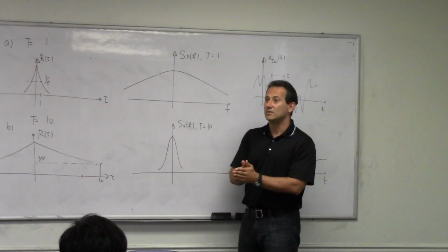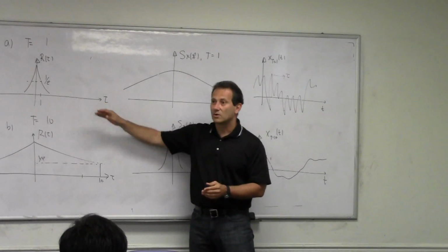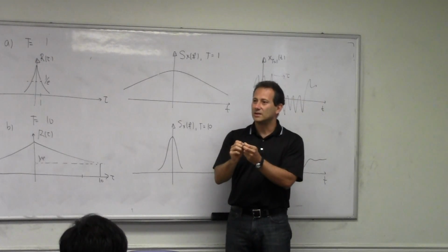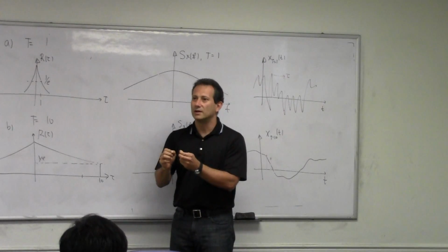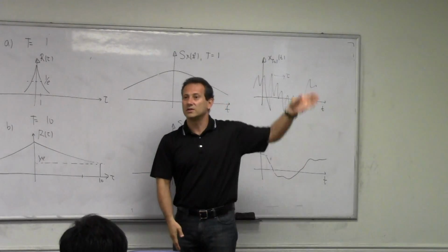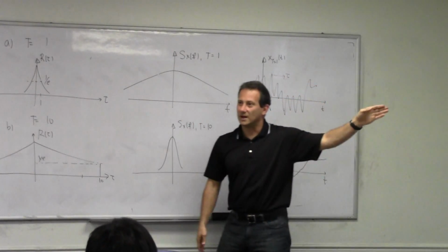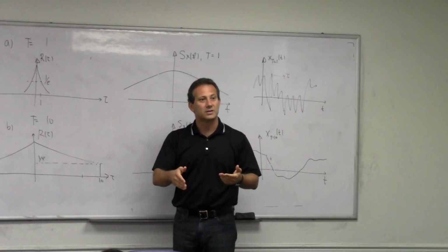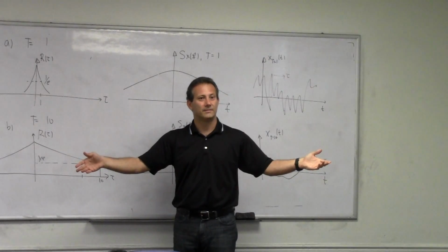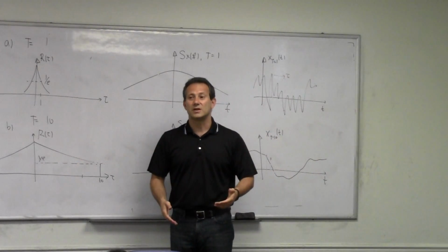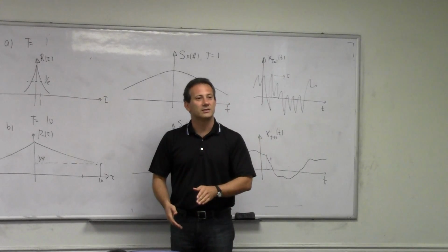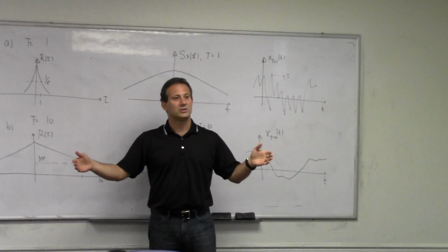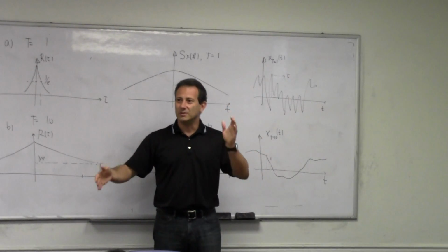Let's take a look at the other extreme. A signal that has an autocorrelation function that's a delta pulse, meaning that even the smallest displacement of this signal, like I take the smallest step tau, what I have here has nothing to do with what I left tau away. What is the power spectral density of that signal? It's constant, right? To build such a signal that changes infinitely fast in the time domain, I need all possible frequencies. And so these are obviously two extremes. All the other signals are going to be in between these two extremes.